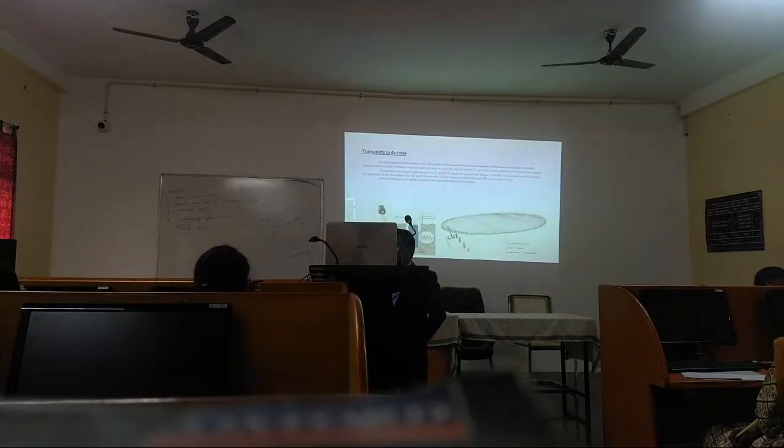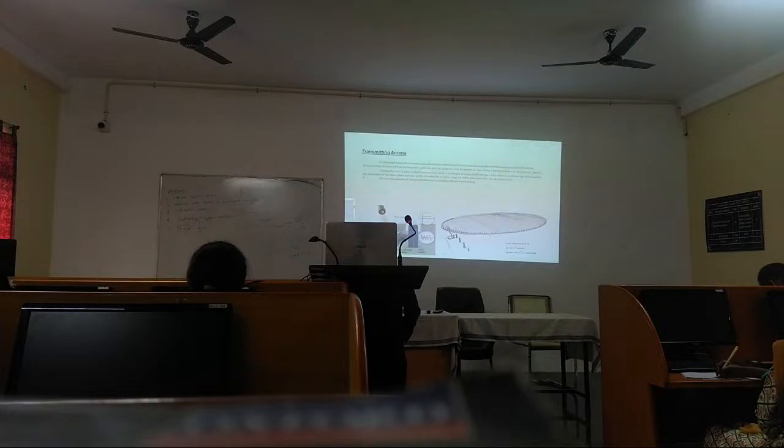So maybe 13 kilometers, whatever is in reality, taken from Wikipedia as well. So here the measurements of this antenna are 13 kilometers north-south, 10 kilometers east-west, the rectangle. So 23 milliwatts per centimeter square maximum, that is 0.003 watts per meter square. Less than 1 milliwatt per centimeter square at the rectangular edge.